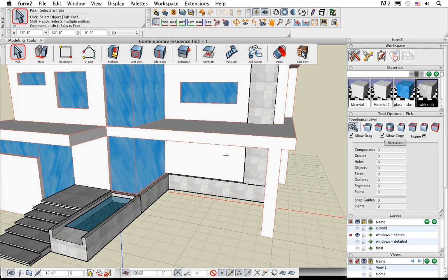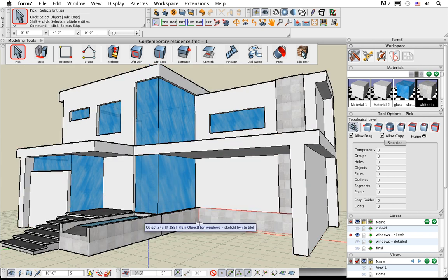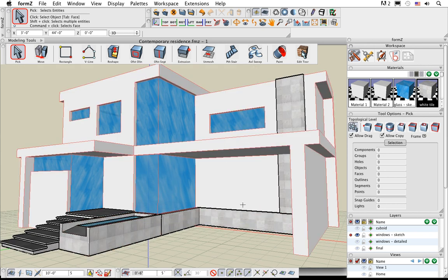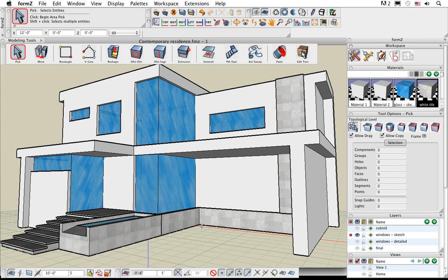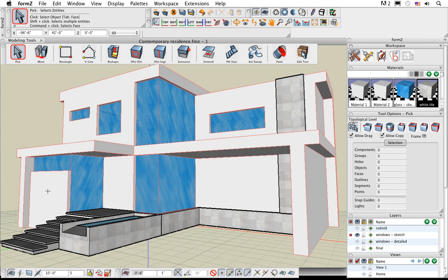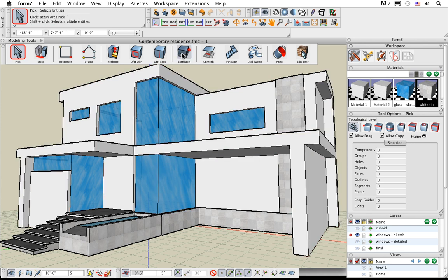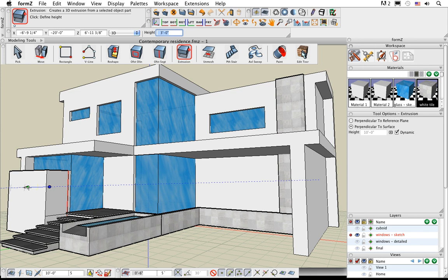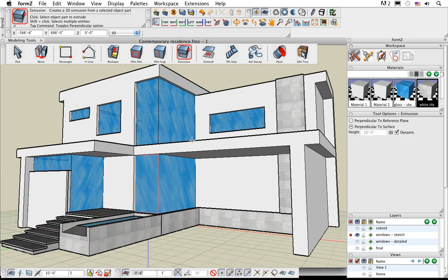That's pretty easy. Let's go ahead and look at our front perspective view again. I sort of like the white tiling to balance this out. We have it all shifted on the right-hand side here, so maybe we'll put a little more stone on this side over here. Once again, use our 3D derivative tool, take that existing part of the wall that's there, extrude that out to create a new object that we can then apply our stone tile to. There we go. So now we've got a little bit more balance with that tiling feature on the front facade of our building.